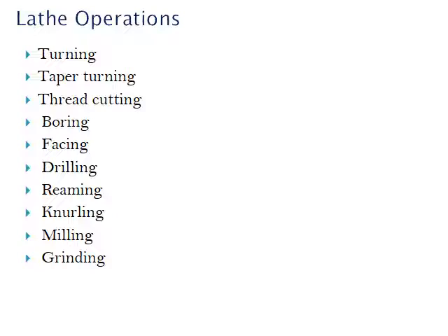Okay. So the boring operation means enlarging an already drilled hole. It usually uses a single point cutting tool to enlarge the hole. Actually the requirement is 25 mm, and the standard drill bit available in the market is 24 mm. So 1 mm material you have to remove with the help of boring operation. That's why an already drilled hole is enlarged as per your requirement. A very small amount of 1 mm material is removed and the drilled hole will get 25 mm as per your drawing. So this process is called boring operation.